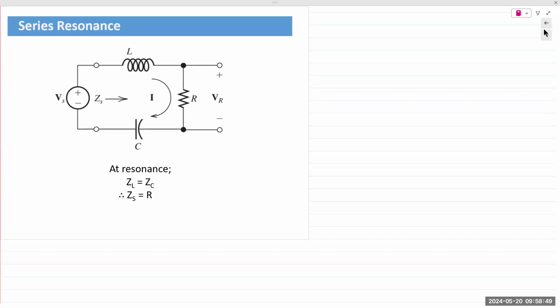So when you first flip on the switch and apply power to a circuit containing R, L, and C, in the positive half cycle energy flows into the inductor, in the negative half cycle it flows out, but in the negative half cycle energy flows into the capacitor. And so it bounces back and forth between the two. At one particular frequency, depending on the values of the inductor and capacitor, there could be voltages and currents larger than the input voltage that appear in the circuit.